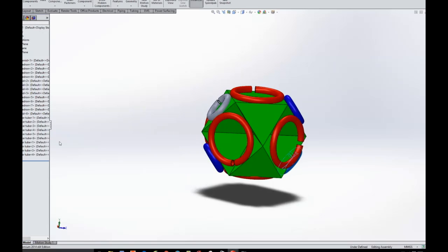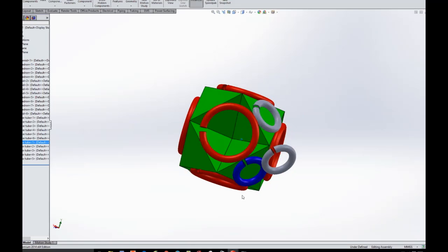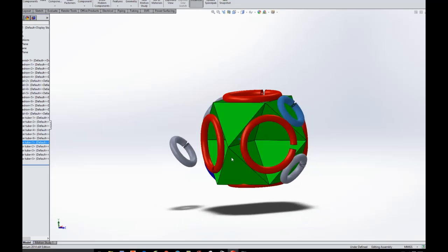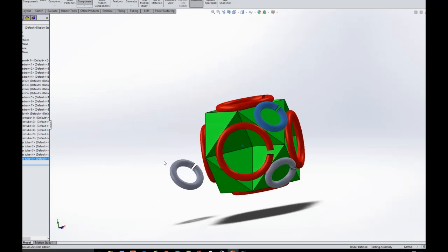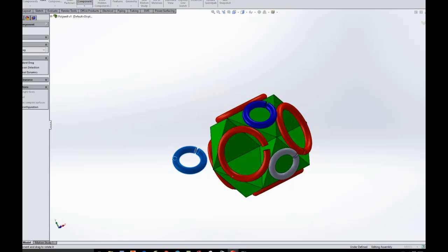It would be like a short circuit, and you wouldn't get the same magnetic field through it as if the wires were slightly separated. Generally they put a coating of varnish on them, which separates them electrically so they don't arc out between each other. They could make a connection, and that makes the magnetic field in that part not as strong as having individual wires.